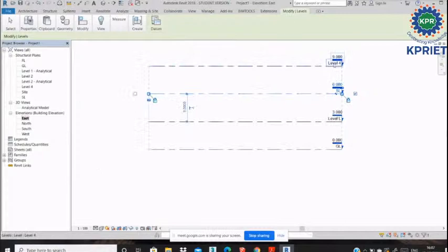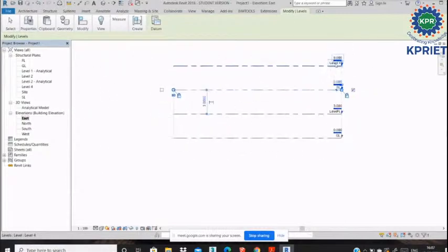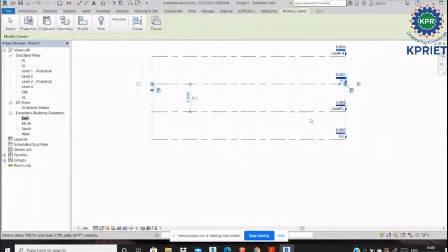You change the name of this level, right? You click this level, double click, you change the level. Second step is all right. First step is unit setting. Second step is going to elevation. Click this east, then go to elevation east. Click this level, then go to create similar, then go to opposite, changes one by one, right? Okay, now second step is over, right?